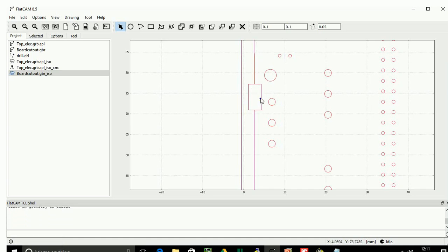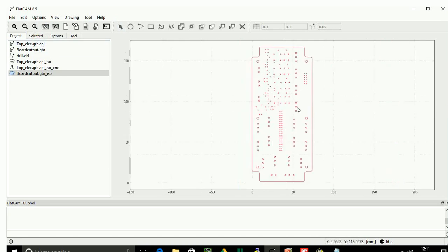So that's selected, this is selected, and this is selected, and then you press delete, then you go to edit and update geometry. So that part, the internal path, is gone. So we got our one path which is going to do the cutting.